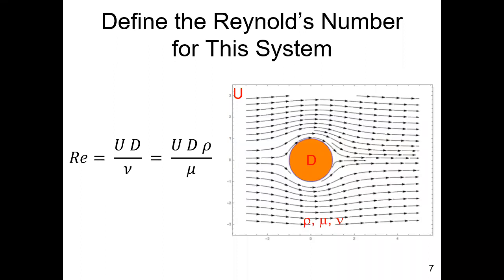When you had a laboratory exercise where you were calculating Reynolds number for flow in a pipe, you basically used this equation. The length parameter was the inside diameter of the pipe. Again, Reynolds number is always a ratio of forces, and those are inertial forces to viscous forces. And it's always the velocity times length divided by kinematic viscosity. So we're going to start at a very slow velocity, where the Reynolds number is 0.01.